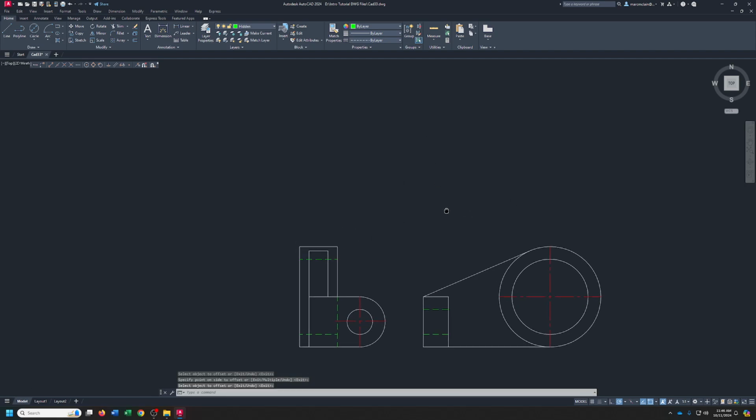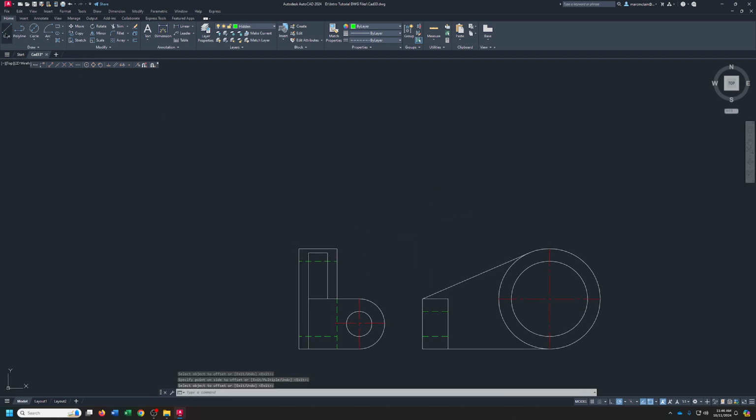So I've got our front, now we've got to get the top. All right, so change to my construction line, go to lines. I want to line up with this one, okay? I'm going to start here, and I'm going to come up 1.5. That's where I'm going to go to, okay? So now I know that from here to here is 2, and then that's another 1, so I've got to come out 3. Change back to my object line.